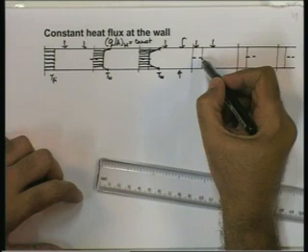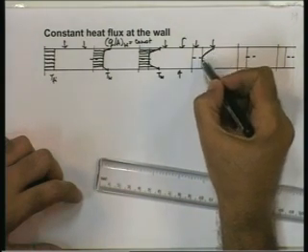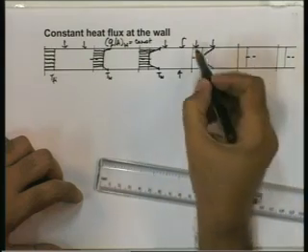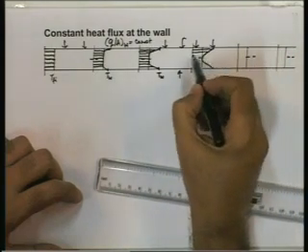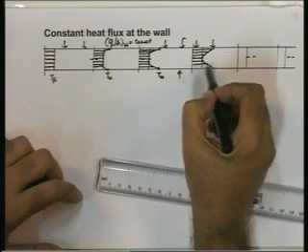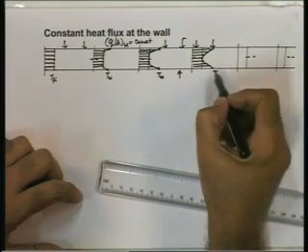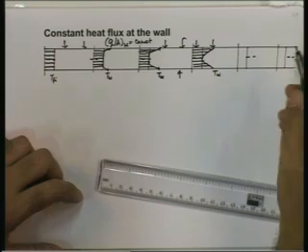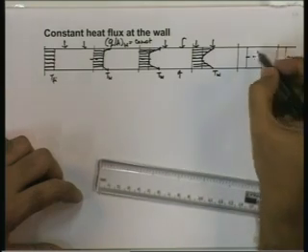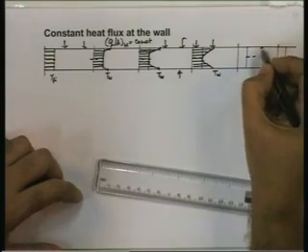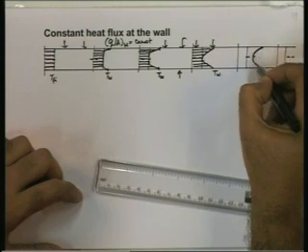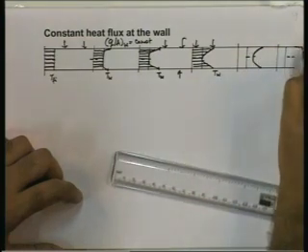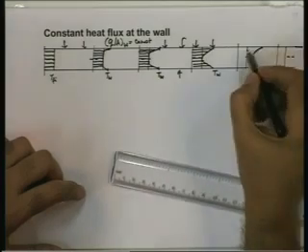You will reach a stage where perhaps the penetration of the wall effect is through and through. The wall temperature here would still be higher. And after that, the gradient at the wall will remain the same, but even the center temperature would go on increasing.